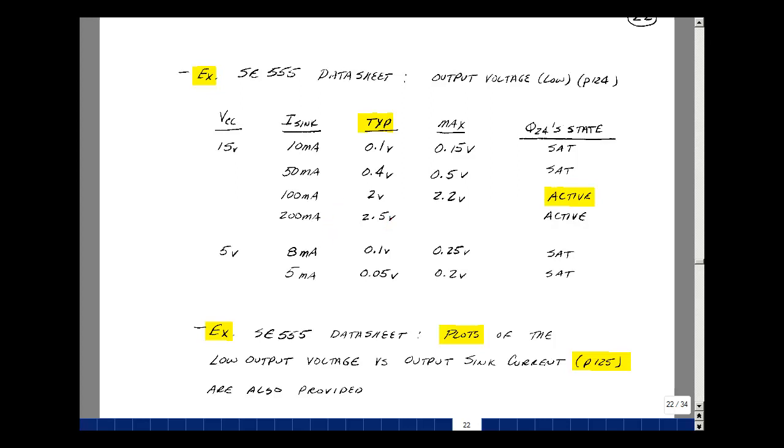The thing I should point out with the 555 timer, there is no current limiting protection on it. So our 741 op amp shuts itself off when we exceed about 25 milliamps plus or minus. The 555 timer will just simply melt if you pump current into it. Fortunately, the first time I played with it, I thought there was a current limiter, and I watched my board and my chip just melt. You'll learn by sometimes smelling your circuit. Of course, if you change the power supply, those numbers will actually change too.